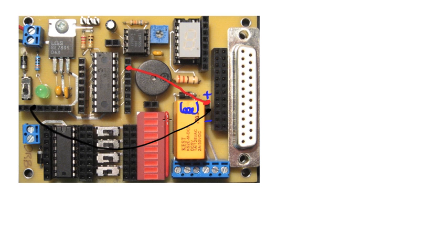So here's what we'll have to do instead. We will need to make a connection from our negative connection on the relay and take that to one of our ports, and then take the positive connection and go over to our plus 5 volts. And in this fashion, with this microcontroller, with this relay, this will work.